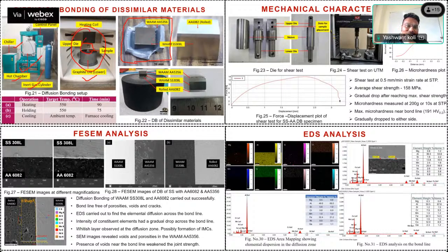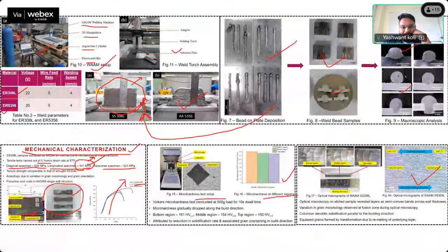The main reason for this first component failure was the fabrication of aluminum alloys using the GMAW setup. I've already told about how we have developed these aluminum alloys. You can see this staircase defect is there. Much porosity was there in this component. This is fabricated using the GMAW process with WAAM, and this aluminum alloy, after cutting, we have seen there are many porosities. The diameter of porosity is too big. So you can visually see the porosity level.